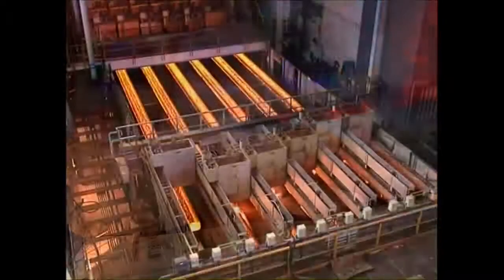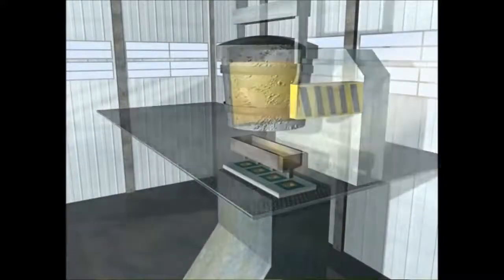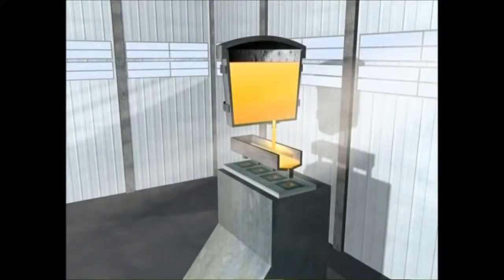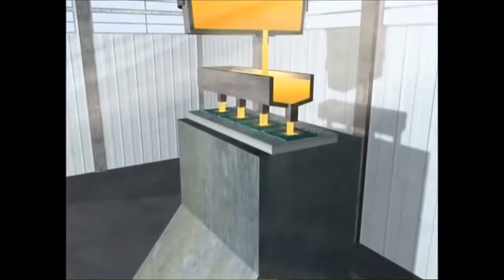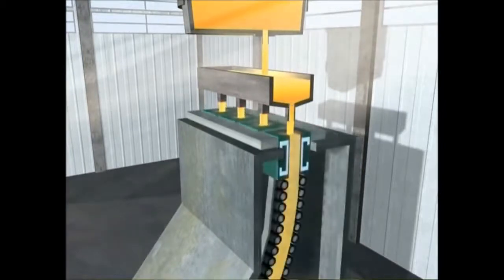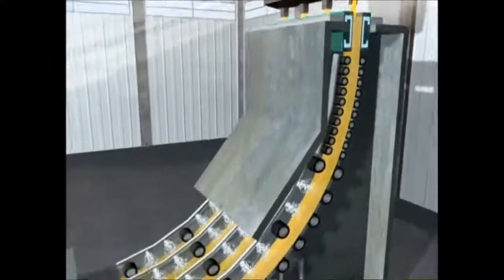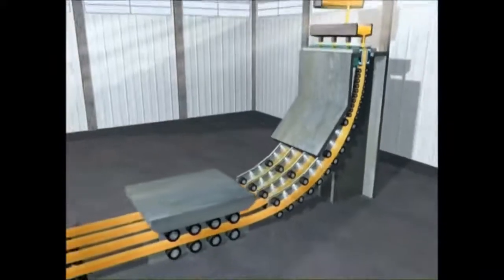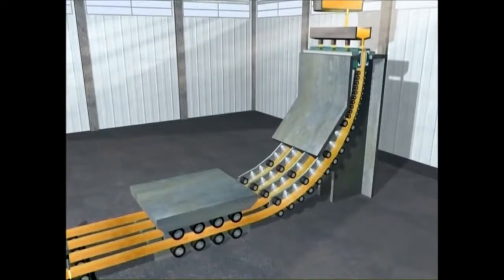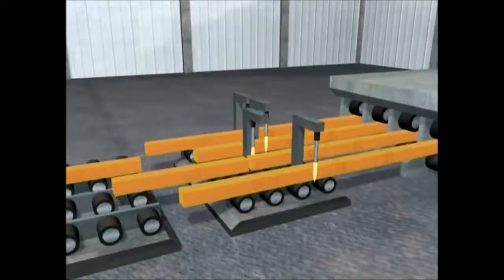Continuous casting is the process used to solidify the molten steel ready for shaping. A ladle of steel is teemed or poured through a gas-tight refractory tube into a tundish. This is a reservoir and feeds the steel through further gas-tight refractory tubes into a number of water-cooled copper moulds. The flow rate is controlled, and with only the outer shell solidified, the steel is drawn from the bottom of the mould through a curved arrangement of support rolls and water sprays. It then emerges horizontally as solid steel strands and is cut to length by automatic gas burners.